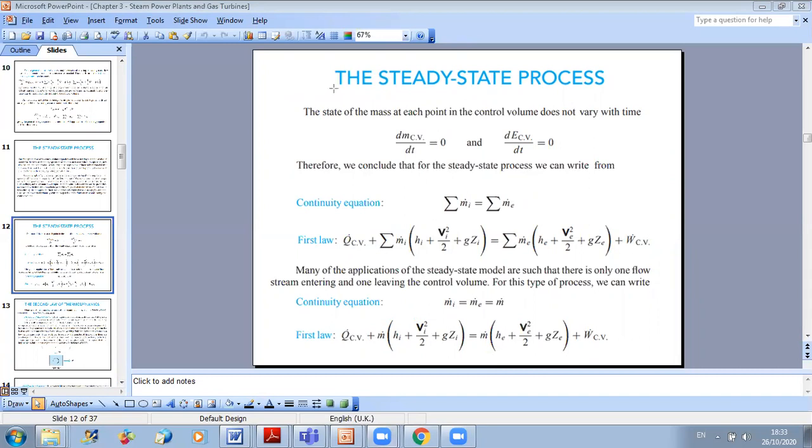First, in a heat exchanger, you have exchange of heat, no work produced, so this term will cancel out. And as I said before, when they don't mention anything about potential and kinetic energies, you can neglect them. But pay attention here. You should not use this one. You should use the previous one.